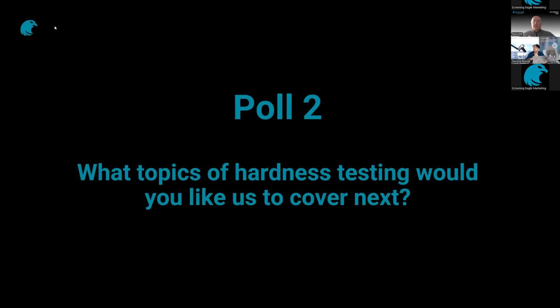So we do have one question. With boiler or superheater tubes, 2 to 3 inches in diameter, which are pretty thin, less than a quarter inch in wall thickness, which method between UCI or Equotip Portable Rockwell would be preferred? And what grip or probe would you recommend for that test method?